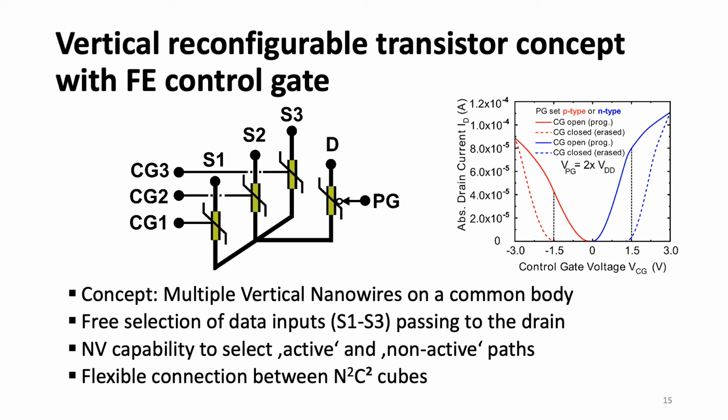If the concept is coupled with a ferroelectric gate layer around the Schottky barrier, the selection of active paths can be stored non-volatile. This way, a flexible reconfigurable input routine between logic blocks can be realized. Here, the concept has been first validated by TCAD simulations.